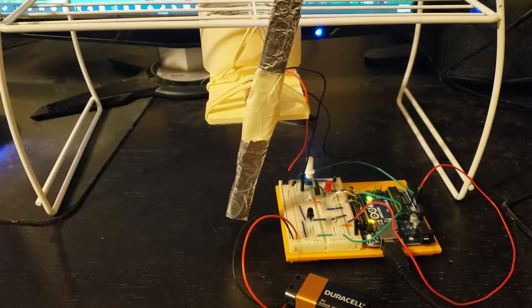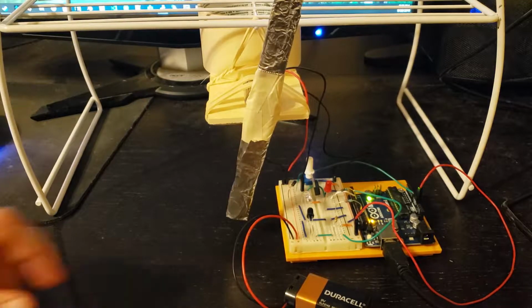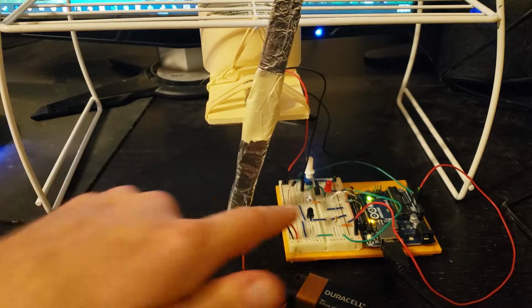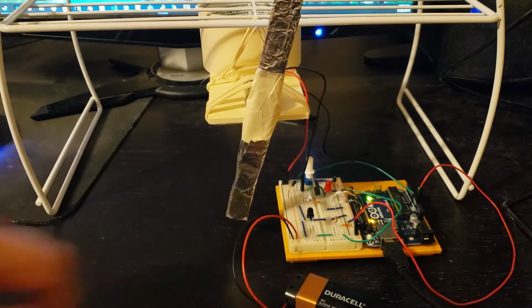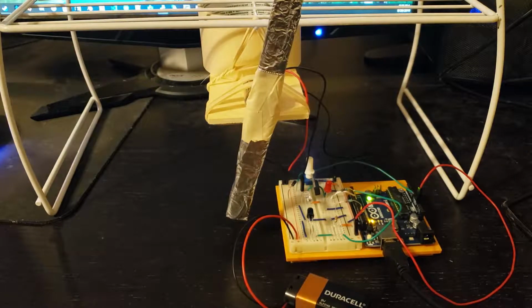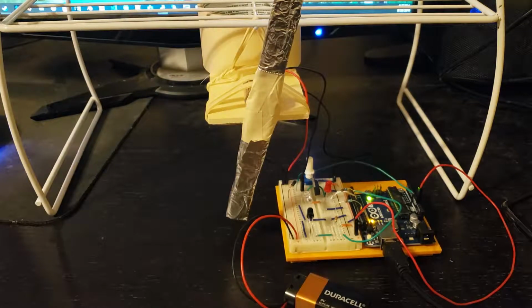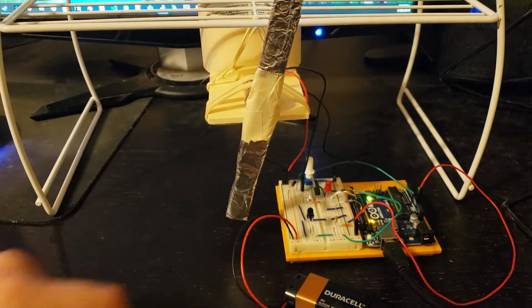I decided to use round robin with interrupts, and I configured the IR detector with a pull-up resistor to trigger an interrupt on a falling edge. You can see my IR detector here and my IR emitter here and the pull-up resistor that I just referred to. The ISR for that IR detector increments a counter and flashes a red LED every time the propeller finishes blocking the IR signal. Here's the red LED that you'll see flashing on and off every time an ISR is triggered by the IR detector.